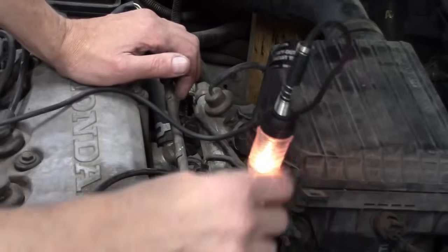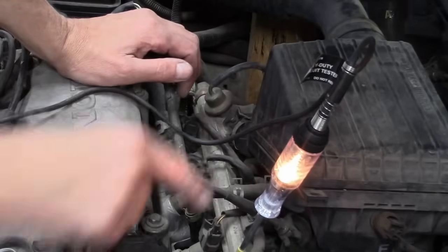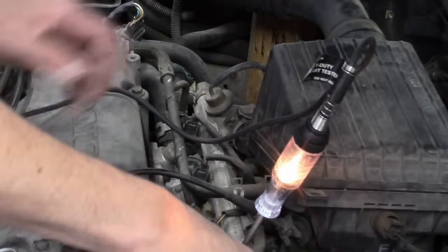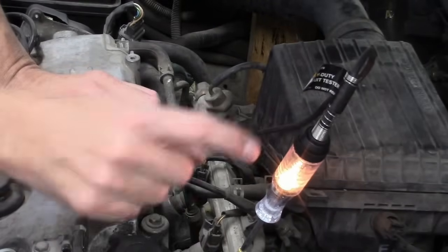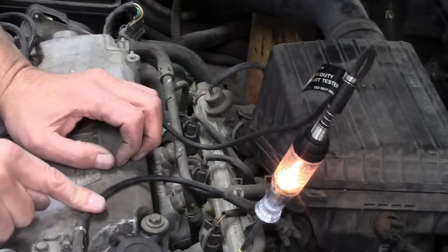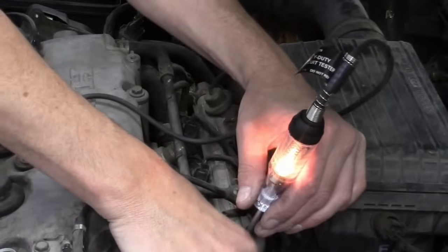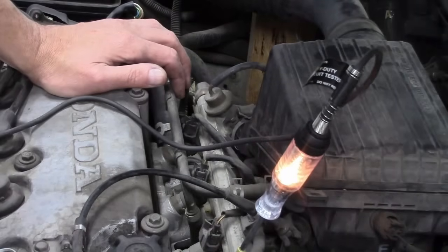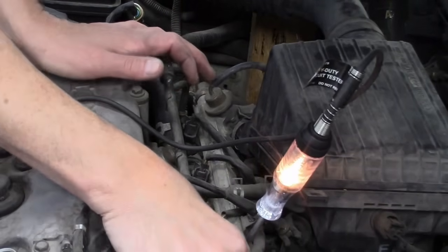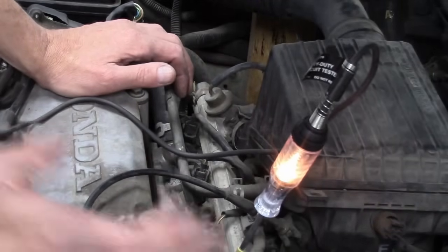Now, it's also possible, of course, that we are on the power side of the injector, and each wire that's a different color is the power. So how do I know the difference? Well, it's very easy. I'm going to just unplug the injector. If I am on a power, that light will stay lit. If I am on the ground, we now lose that power connection through the injector, and the light will go out. And you see the light goes out. So there is no question about it. This is a ground side switch system. We'll probably go ahead and review that really quickly on the dry erase board, but just that simple test is telling me there is no question I am on the ground side of a ground side switch system.